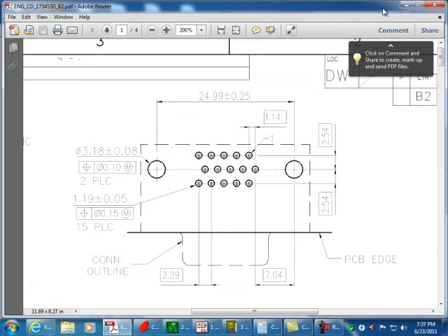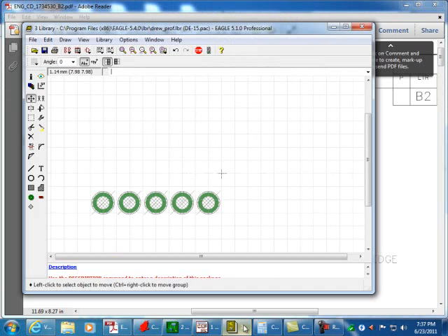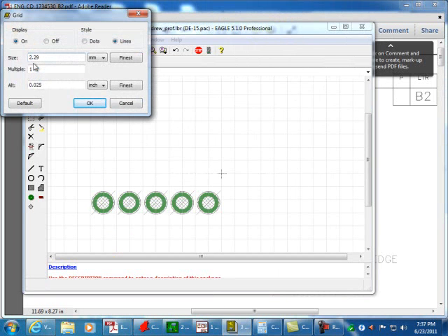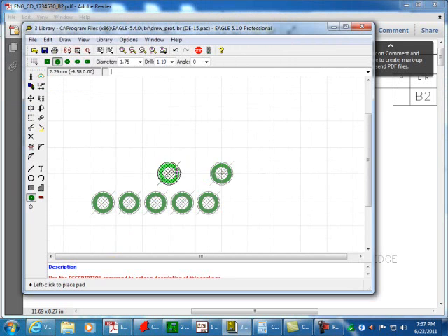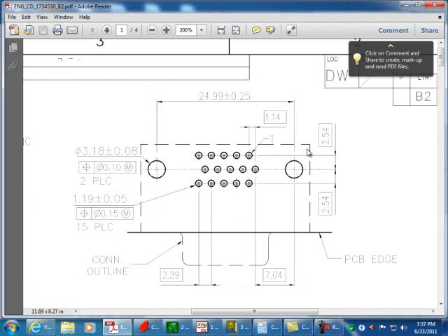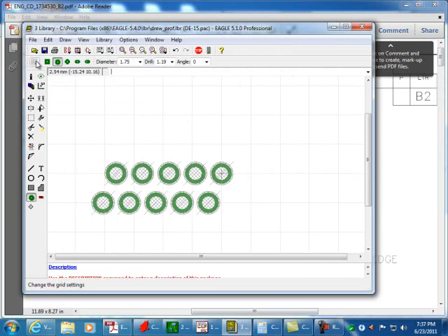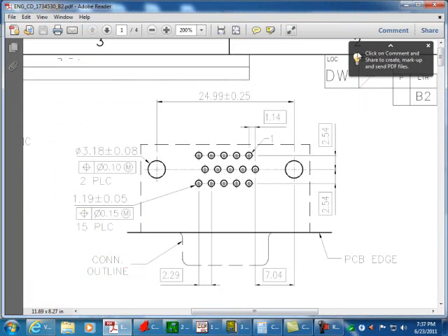And then we'll place our second row of pins. I'll set my spacing back to 2.29 because it's the same there. 2.29. 1, 2, 3, 4, 5. Okay? And according to this, the space to the next row is also 2.54. And we need to shift back by 1.14.